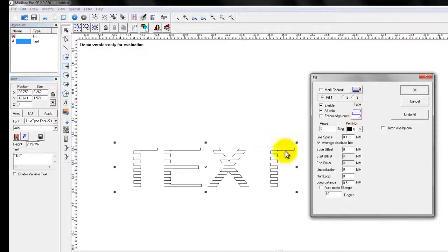So this is going to give you the fastest time, because what it does is it cuts down on what we call jump times, which is jumping between one character to the other where the laser turns off, which can take significant time. You can imagine as the laser jumps all the way across, back and forth, it takes a lot longer than the laser filling the T, filling the E, creating the X, and then creating the last T.